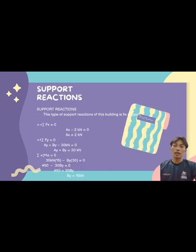So next is support reaction. The type of support reaction of this building is pin support. So there, as you can see, sum of Fx is equal to 0, Ax equal to 2 kilonewton, sum of Fy equal to 0, Ay plus By equal to 30 kilonewton, and the moment, as you can see, sum of moment equal to 0.